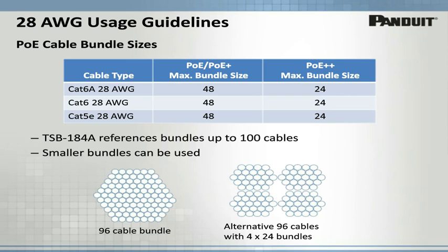Now, just to point out, in the chart above, for current PoE and PoE+, up to 48 28-gauge cables can be bundled together. And for the expected higher PoE++ power levels, up to 24 cables of 28-gauge cords can be bundled together across all three categories of performance.